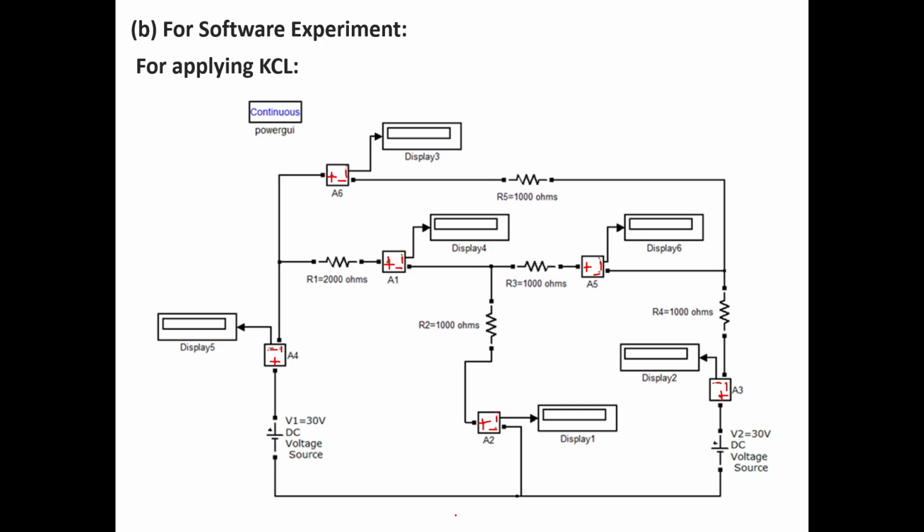And one more thing that you have to remember is that a powergui, you must select a block from the Simulink library. You must type powergui in that, POWERGUI. This is GUI. Okay, powergui. After designing this whole circuit, and after substituting the values in each and every element, at last you must select the powergui, which is continuous type, from the Simulink library, and copy it in your new model in which you are designing the circuit.